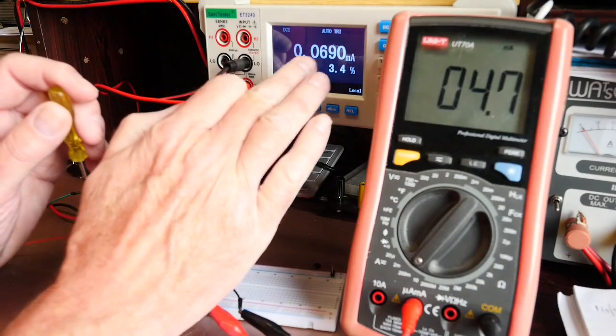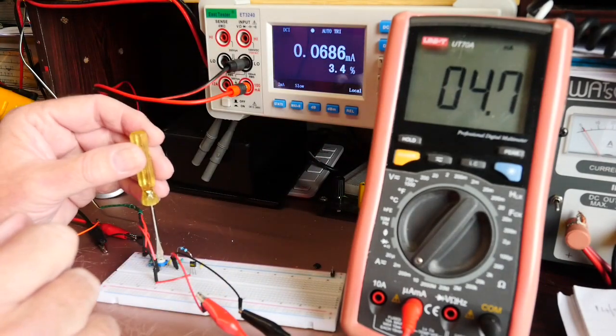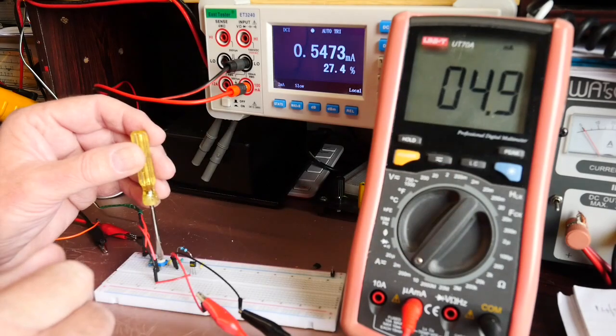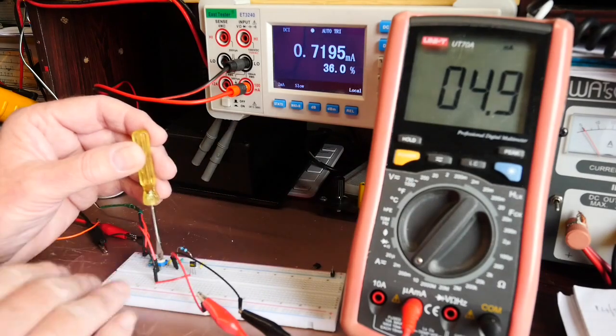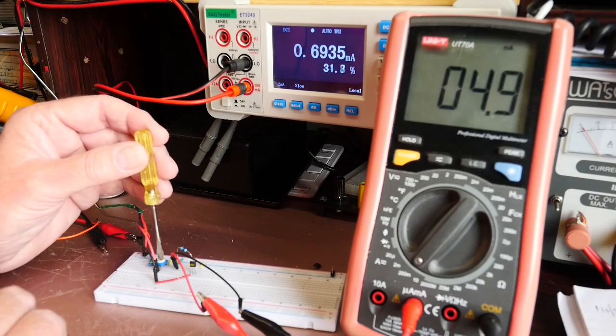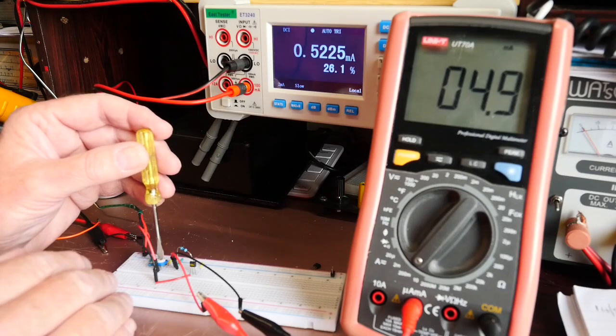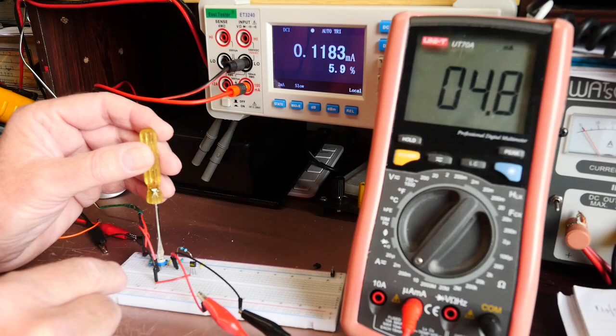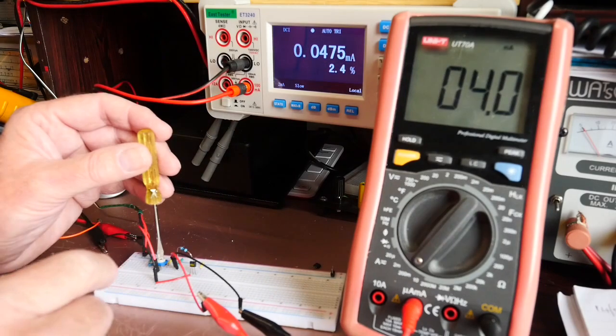So we're still at 0.06 here, and if we continue, even as we approach half a milliamp base current, we're at 4.9 collector current, and no matter how far I go now, it probably won't go any higher because I'm just using a 5-volt supply. But the point I'm trying to make here is there's clearly a point at which the transistor doesn't amplify anymore. So as I come back down now, we're still at 4.8, and it doesn't start to drop until the base current is below about 0.05 milliamps.